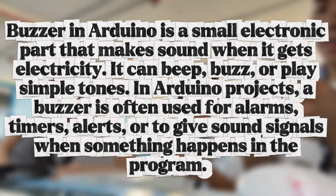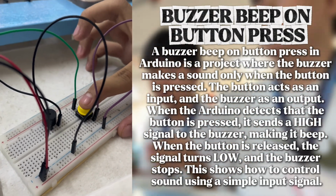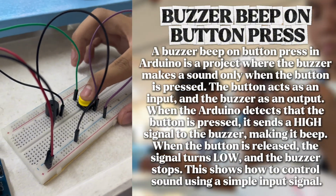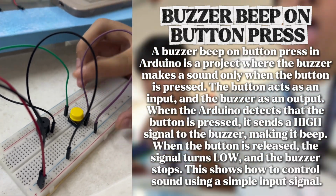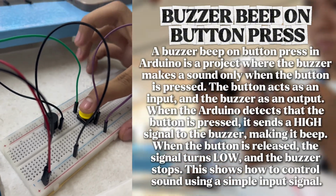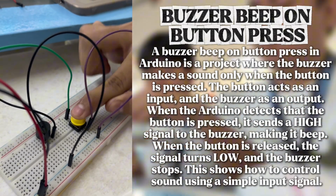A buzzer beep on button press in Arduino is a project where the buzzer makes a sound only when the button is pressed. The button acts as an input and the buzzer acts as an output. When the Arduino detects that the button is pressed, it sends a high signal to the buzzer, making it beep. When the button is released, the signal turns low and the buzzer stops. This shows how to control sound using a simple input signal.